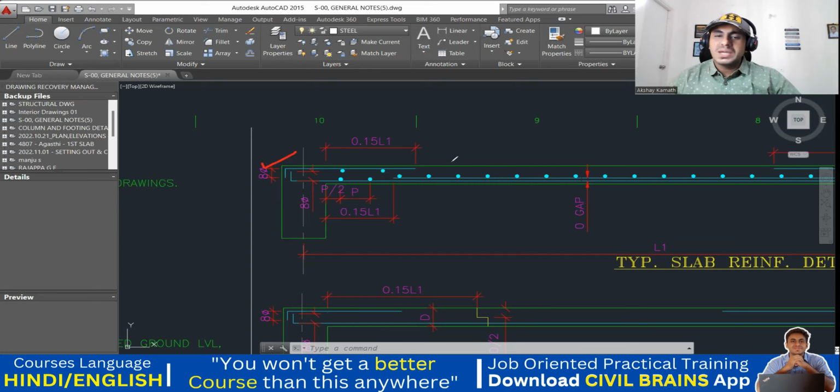If you're using a 10 mm diameter bar, 8 into 10 is 80 mm. So this will be hardly an 80 mm bend you are going to give. 80 or even 100 mm you can give. It's mentioned 8 into dia. Simple. Understood the concept?